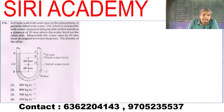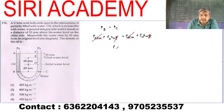So the pressure at B and the pressure at C are same. So pressure at B is equal to pressure at C. So the pressure at B is given by P atmosphere plus density of oil, height of the oil, g, is equal to P atmosphere plus density of water, height of water into g. Then P atmosphere gets cancelled, g gets cancelled. I want the density of the oil. So density of the oil is equal to density of the water, height of the water, divided by height of the oil.